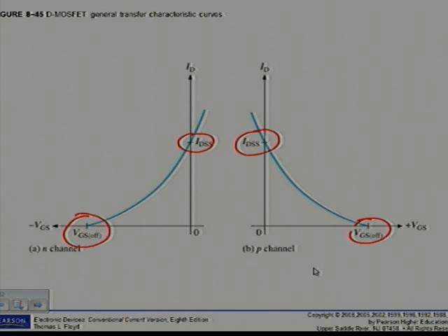The input capacitance results from the insulated gate structure. Excess static charge can be accumulated because the input capacitance combines with a very high input resistance and can result in damage to the device. So, to avoid damage from electrostatic discharge, certain precautions should be taken when handling MOSFETs. There are 5 mentioned. Make sure that you do know them.